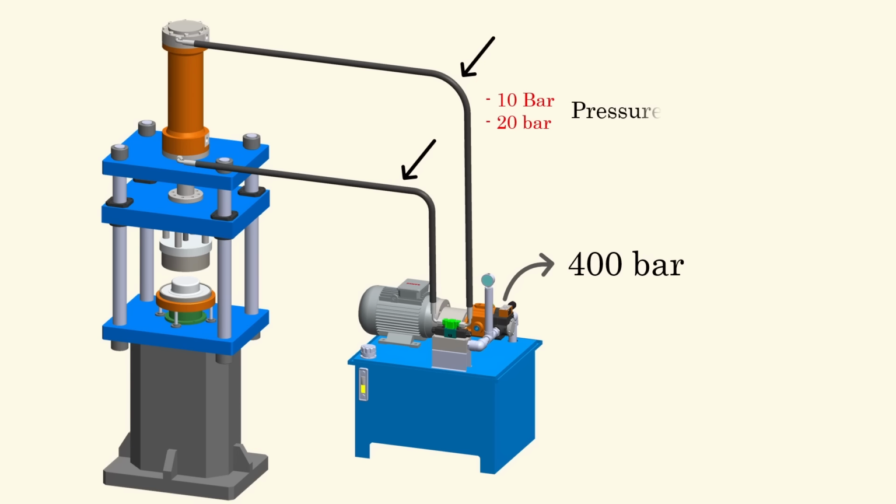So yes, the system will work, but the pressure drop is not only the problem. First, the pressure drop represents a loss of hydraulic energy, which is converted into heat, and the heat cannot convert back into hydraulic energy. So this is the permanent power loss.